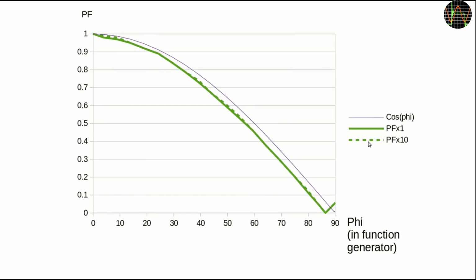So what to make of power factor accuracy? One would expect that measuring a phase angle difference could be done a lot more accurately, but as I mentioned before, this kind of situation is very unusual, as in real life mains voltage and current curves are never very sinusoidal and often extremely chopped up and distorted. In fact, because of that, the chip in the PZEM-004T doesn't even look at the phase angle and instead uses a completely different way to calculate power factor, namely by using the ratio between apparent and active power. This works even for heavily distorted waveforms, but it's more complex than what fits into this video.